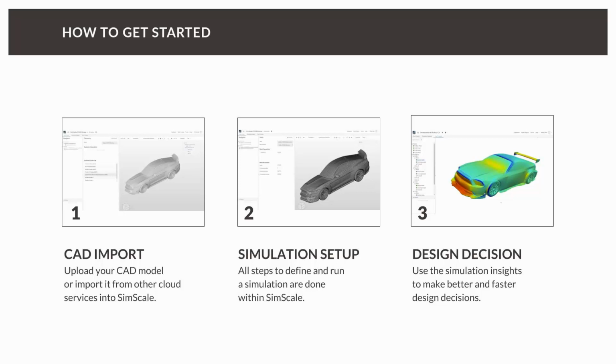And as I mentioned at the beginning of my presentation, the idea of numerical simulations, or of CFD, which is a numerical tool, is that instead of calculating a closed solution for every point around our car, we are only approximating the flow field around the car. And therefore we need to discretize our domain into 3-dimensional cells. And this process is called meshing. And the finer the cells are, the higher is the resolution of our simulation.